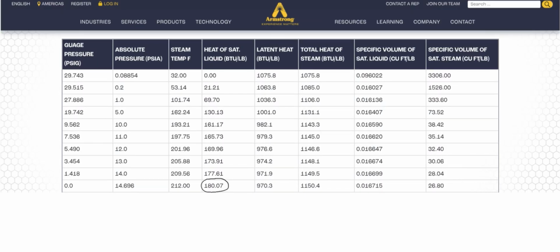So here we can access first the steam table so that we don't have to just rely on a linear BTU calculation, our delta T from boiling point 212 Fahrenheit minus the initial temperature 50 degrees Fahrenheit. So if we use a linear calculation, we're multiplying the delta T times the amount of water in terms of its mass. So 1 pound times the 162 degree temperature rise to boil. So that 1 pound of water theoretically will require 162 BTUs of heat.